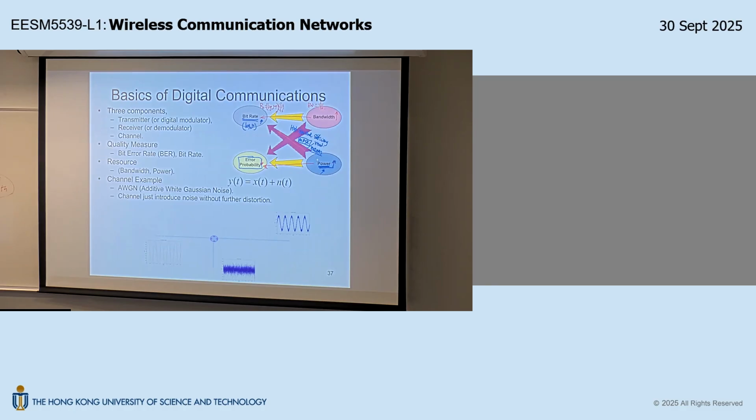So instead of operating at 30 dBm, let's say I operate at 20 dBm only. So I leave 10 dB margin for this peak to arrive. And let's say my average power is now 20 dB, and then when the peak arrives, it becomes 30 dB. And even that is still within the linear region, right? So I won't have clipping in this way. This is called power back off.